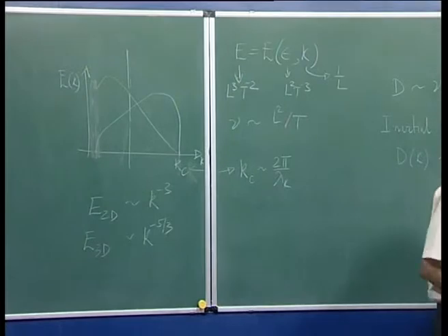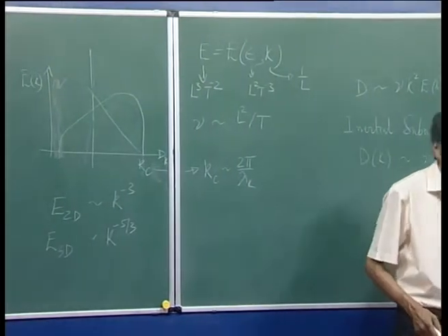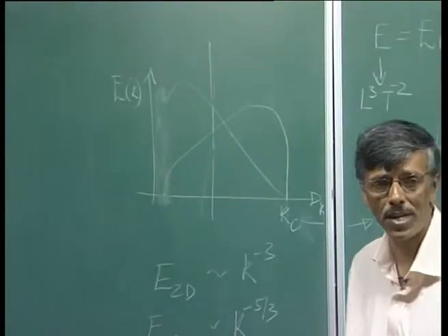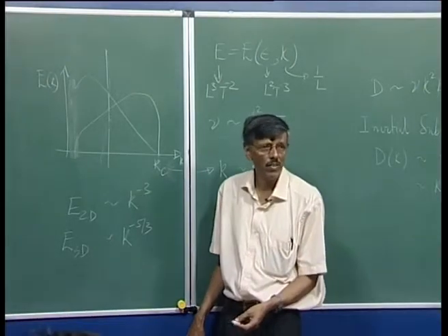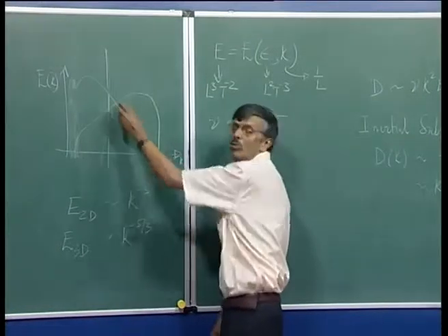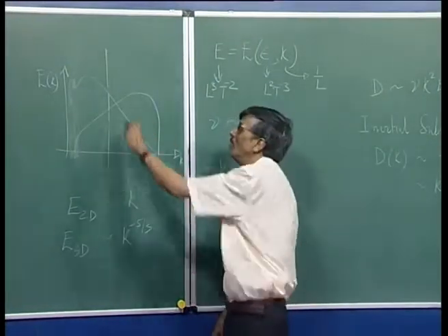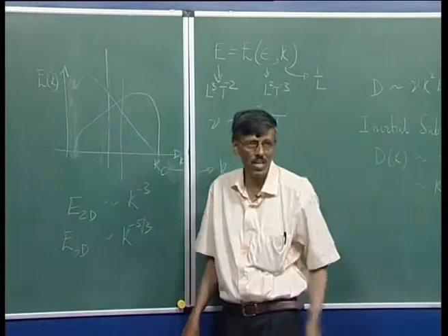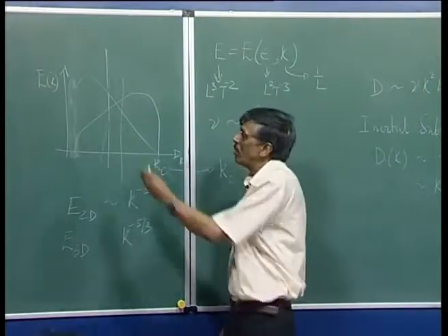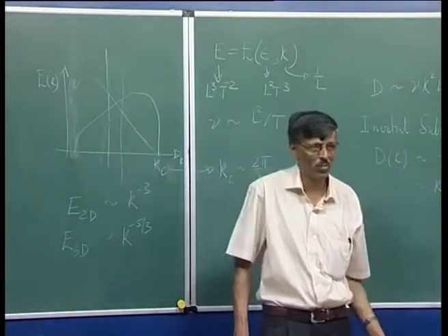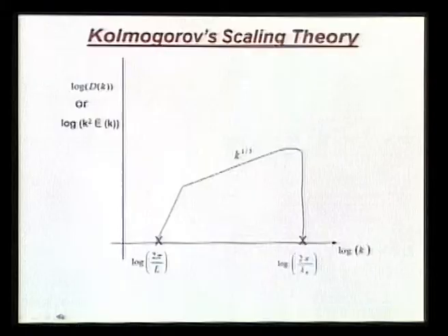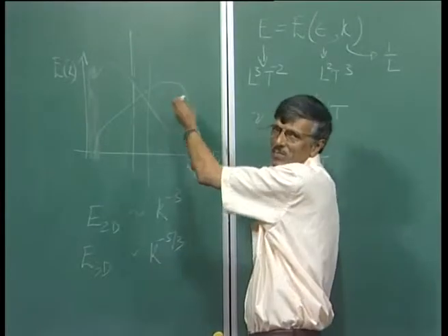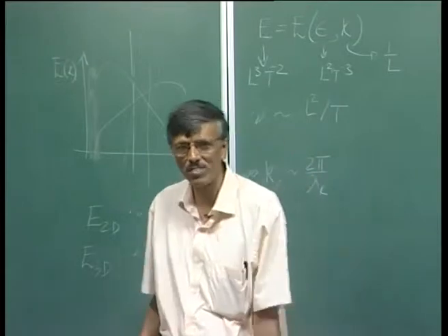So you see, this is important in computation, that people tend to think that I will do LES and all I need to do is worry about E of k. I will short circuit this E of k somewhere and I say, oh, I am doing it. But people do not talk about what they have to do correspondingly to the D of k. But the D of k has this structure, and D of k is more important maybe in the scale which is beyond this. So that is at your subgrid scale.